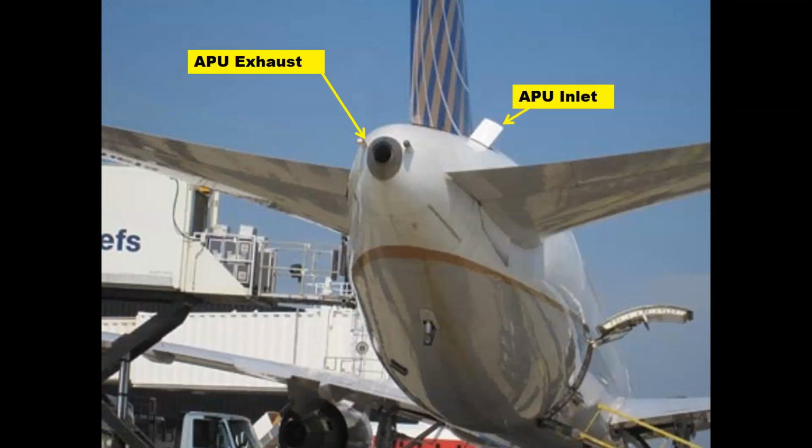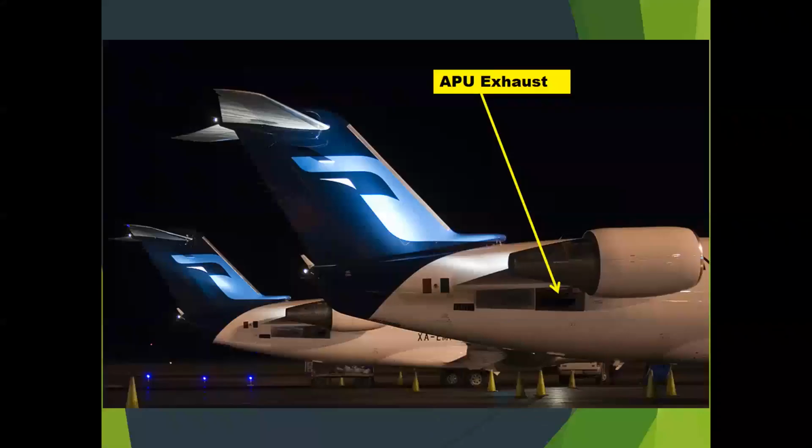In some cases, if the APU is a little bit further forward, here's an example of a plane where the APU is further forward. In this case, the APU exhaust is here below the engine. So rather than being located in the very back of the tail cone, it's more in an aft equipment bay area. Again, this is not a super common design, but it is out there. And that's why you can see, behind that APU exhaust duct, there's a big gray rectangle. Those are all titanium heat shields so that the aluminum underneath isn't damaged by the hot exhaust.